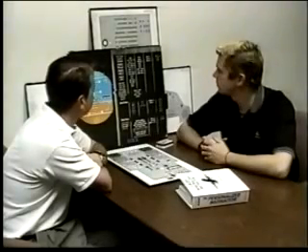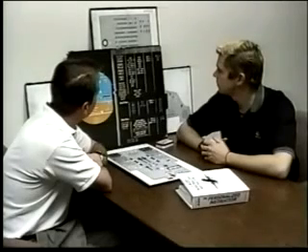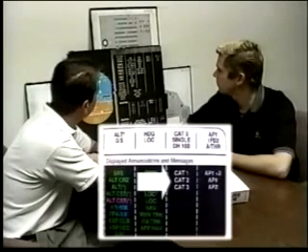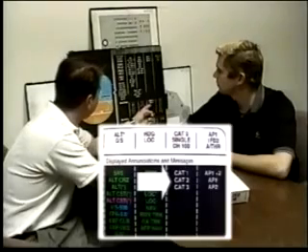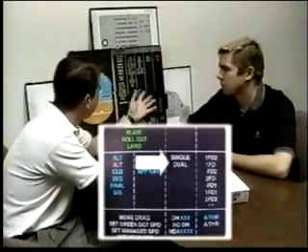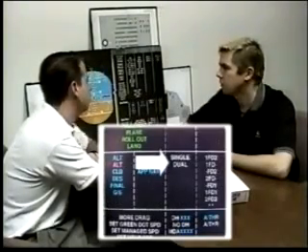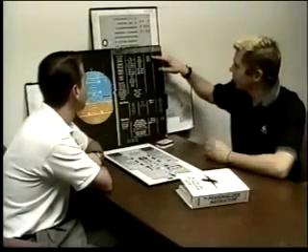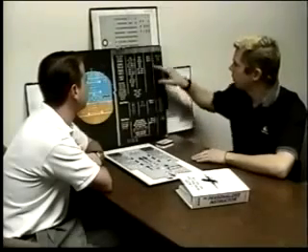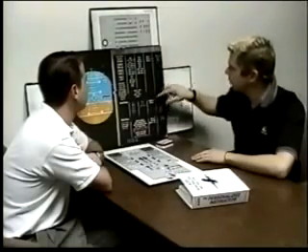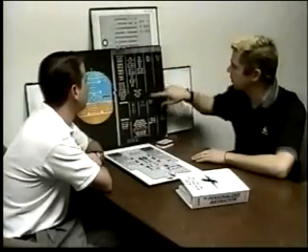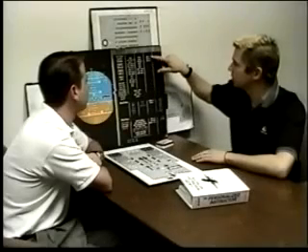Fourth column, approach capabilities. We have Cat 1, Cat 2, and Cat 3, and then you have on your second line a single and a dual. Explain to me the modes that we get on the Airbus. Okay, we only get four really. We get Cat 1, Cat 2 alone, or Cat 3 single, Cat 3 dual. We'll never get Cat 3 without a single or dual, and we'll never see single or dual associated with Cat 1 or Cat 2. Cat 3 single means we can shoot a Cat 3 approach and autoland.